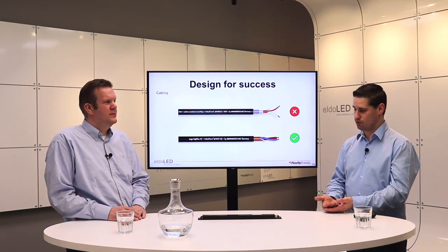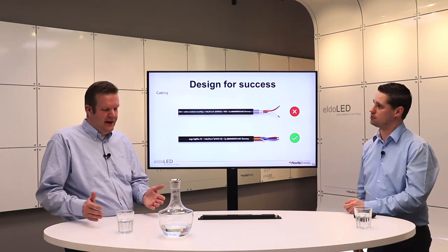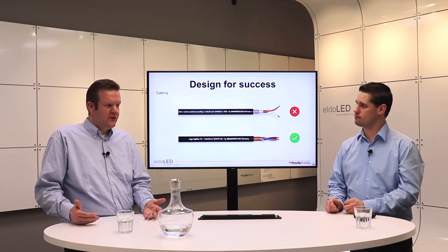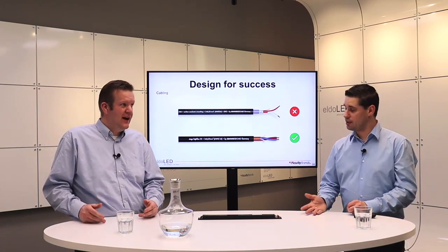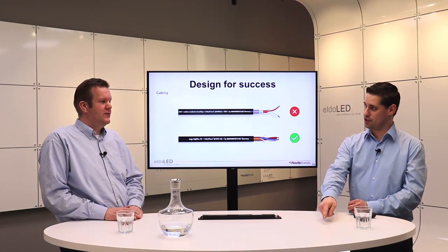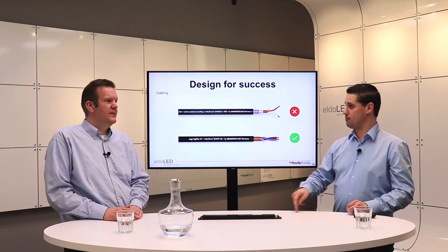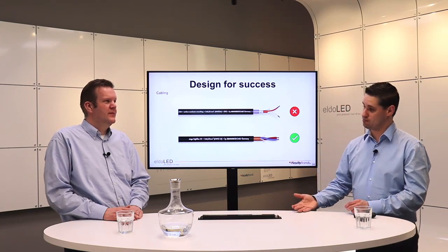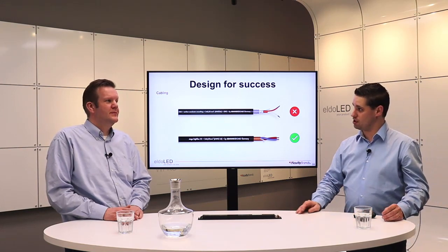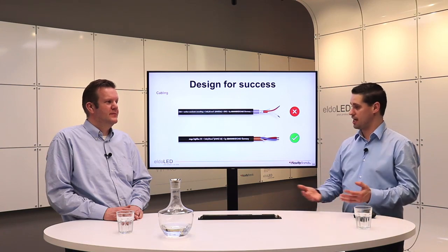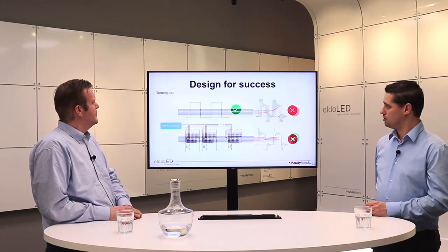From that moment on, you get all kinds of strange side effects because you used the wrong cable. So it can happen that a cable between luminaire number 1 and 2 picks up so much disturbance that luminaire number 32 gives an error or a glitch or a flash or whatever. Exactly. That signal is distributed from the control via every luminaire. So the luminaire at the end of the cable might be influenced by the noise that's entering at the beginning of the cable. So the whole installation needs to be equipped with proper cabling without any star or T-splice connections in the cabling. Good point.